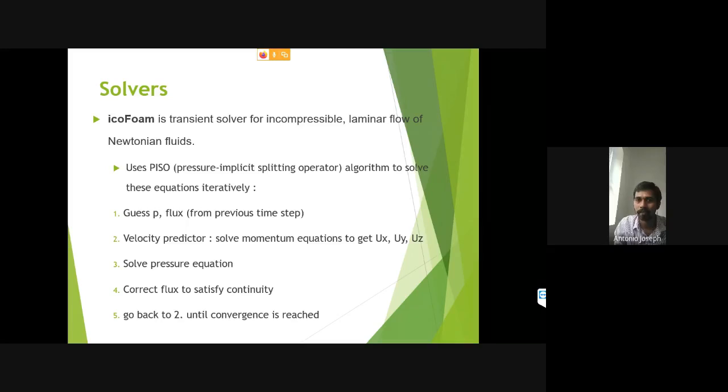We have a mesh quality dictionary also, in which we have specified the quality that we are expecting. While meshing, these iterations happen and it checks whether the quality is met or not. So we don't need to bother about the quality of the mesh we are creating with snappyHexMesh, because we already have a quality dictionary file where we have control over the quality.